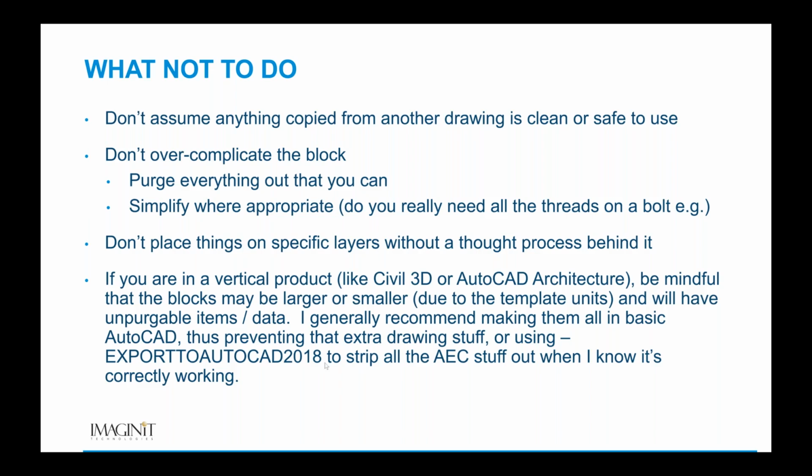The reason why I say this is that if you have a simple door drawing, we're going back to doors, and you do it in AutoCAD Architecture, that drawing might be much larger than the containing geometry because of all of the extra stuff that goes into AutoCAD Architecture, or like Civil 3D, where you have all the styles. So it's best to export to AutoCAD. You'll see the block size drop significantly from that point, and then you'll have a much smaller, more nimble block that doesn't create a lot of bloat in your drawings.